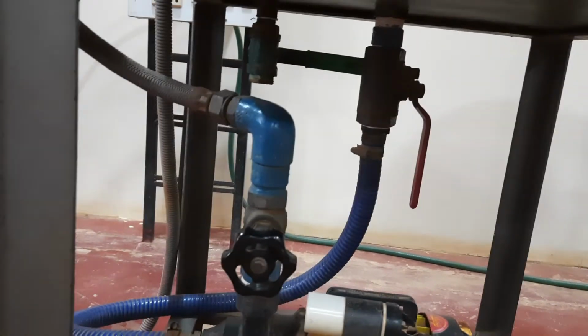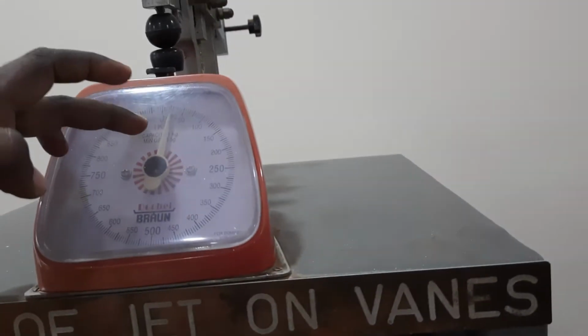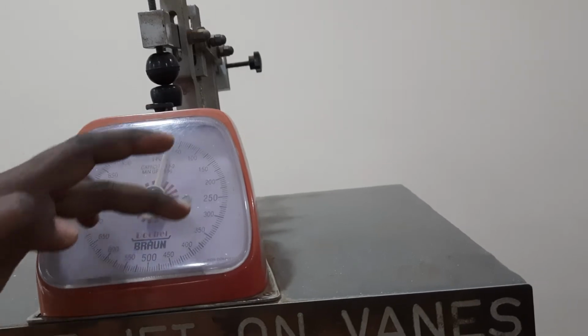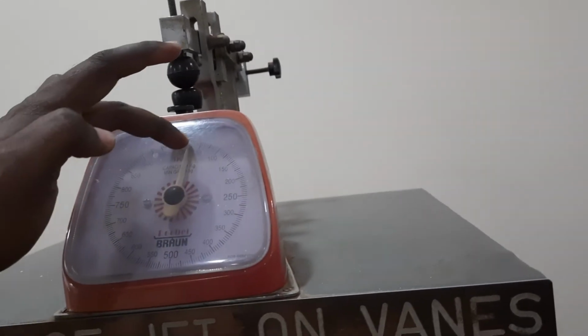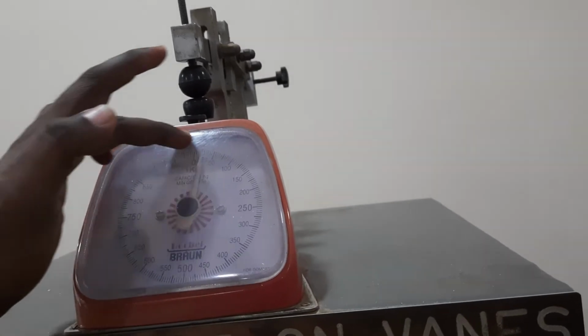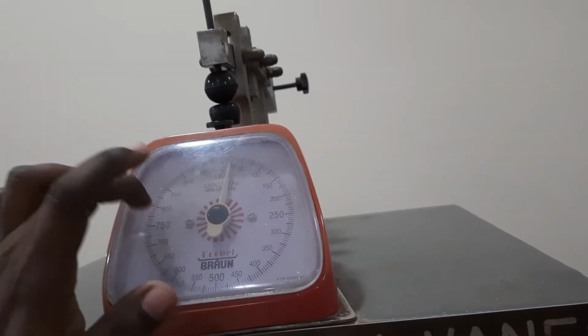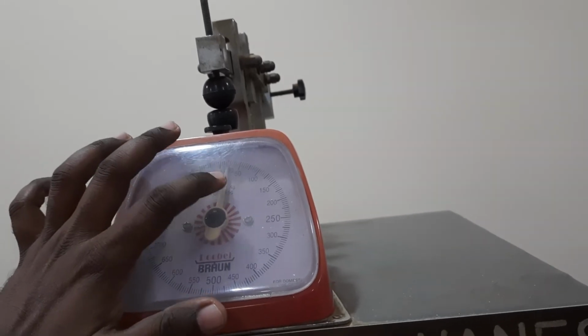How much are you supposed to open this valve? You have to open it till your rotameter reads 10 LPM, 10 liters per minute. Till it reaches 10 LPM, you have to operate this knob. After that, you can see the water will impinge on the blade that you have fixed. The water through the nozzle impinges on the blade, and because of which there will be a load applied on the scale. And remember, this scale will be in grams. You have to later convert it into kg, then multiply by g to convert it into Newton. So whatever readings you get will be in grams.